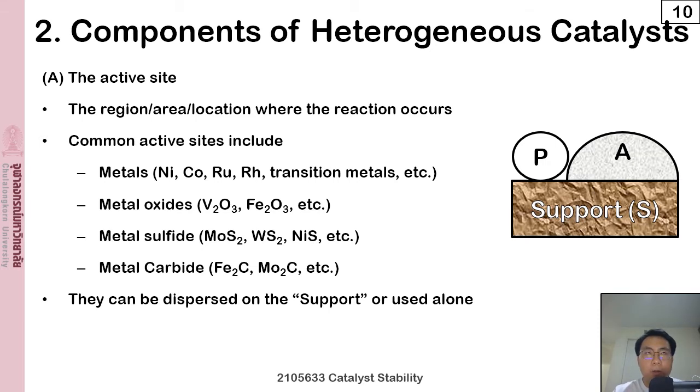Also, when you pack the catalyst into a packed bed or a fluidized bed, you will need a support which can bear the attrition or the crushing between the packed particles. The support has a lot higher strength than the active site itself, so it's common to use the supported catalyst.